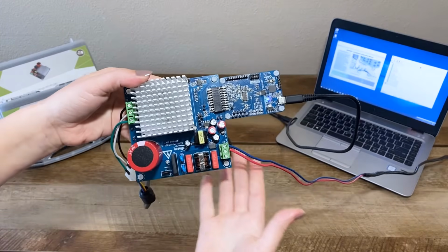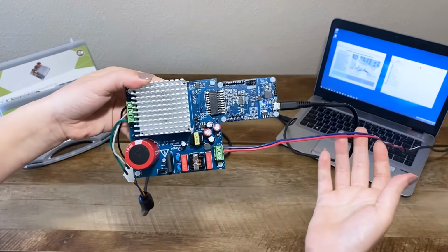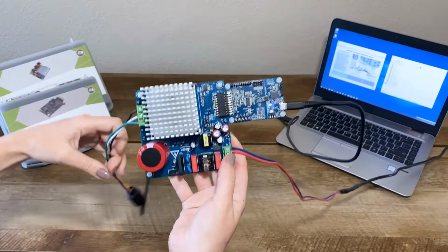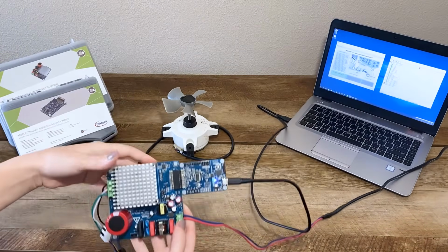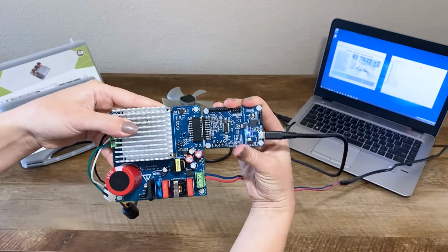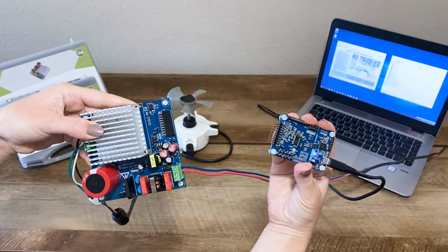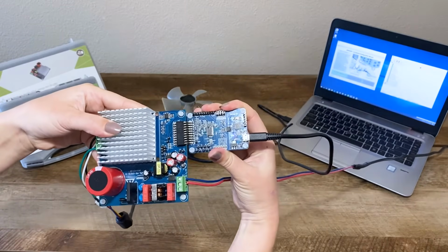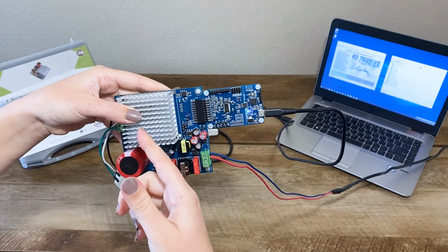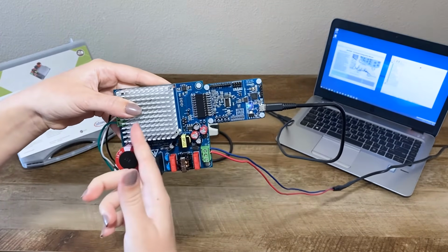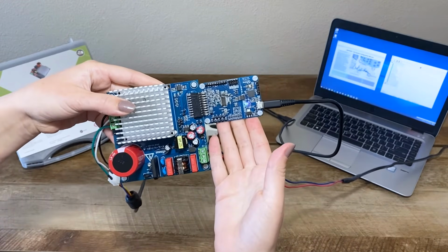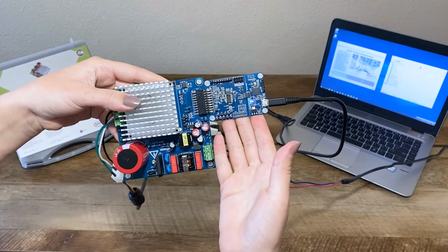This power board includes all the necessary circuitry to operate on an AC source, which is connected here, and output three-phase power here, which connects to your motor. These MADK boards are designed to be compatible with one another and easily connect through the standardized M1 pin connector here. The iMOTION control board not only outputs the PWM signals for each IGBT or MOSFET, but also receives inputs from the power board like your bus current and voltage, the device temperature, as well as fault signals.